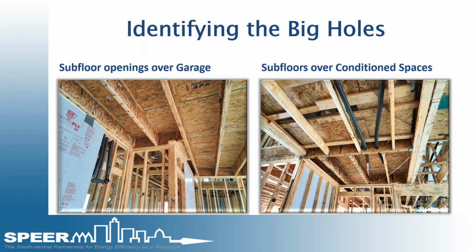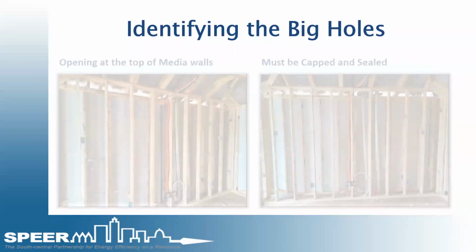And then on the right-hand side, it may be a little difficult to see. This was actually a dividing member, a TJI, that separated a conditioned floor from an attic space. Where I was standing, I'm looking up into the attic. Those are service decking boards that you see there. Any penetrations through that TJI running from left to right need to be sealed to keep anything from the unconditioned attic from rushing into that subfloor, showing up on the blower door test, and affecting comfort, and to avoid having that as a breathing hole into the attic.